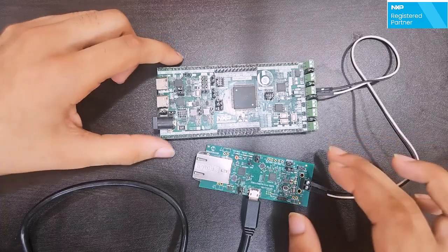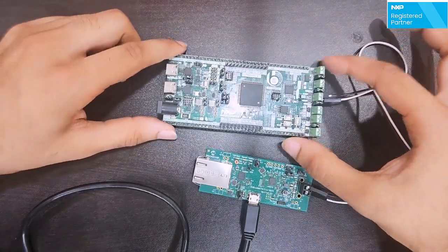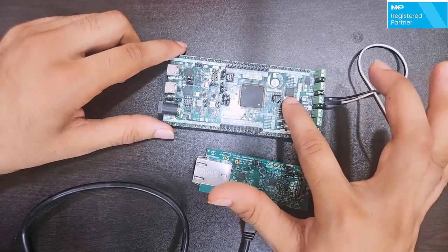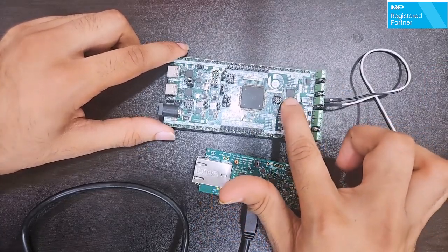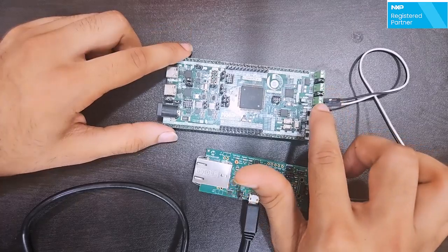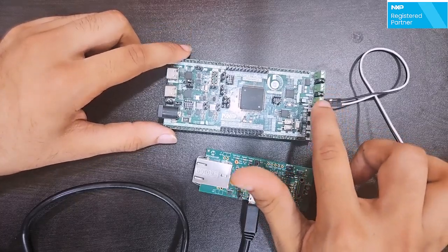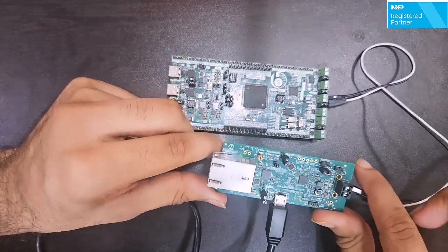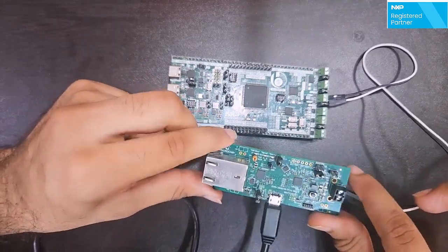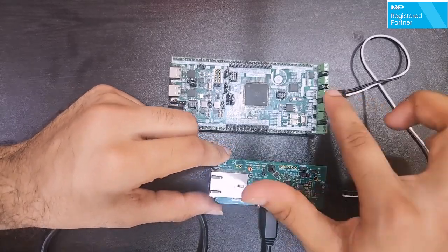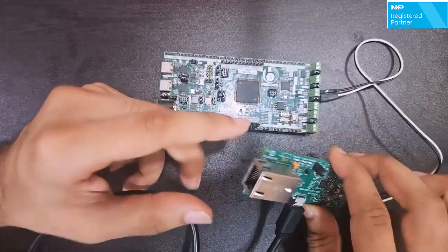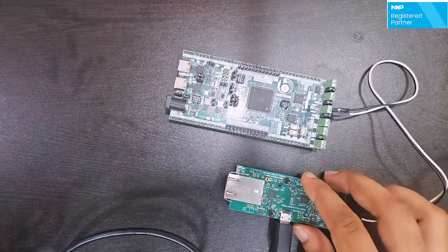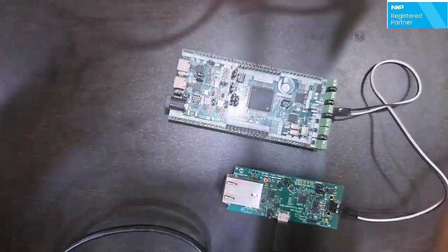Now, in terms of the connection, this is our Autoboard version 1, and as I told, this is our main controller K344, followed by an Ethernet transceiver IC TJA1103 of NXP Semiconductors, followed by a 2-pin terminal connector for connecting the automotive Ethernet. And this is the Ethernet media converter of Microchip Technologies, which is used for converting the automotive Ethernet to the standard RJ45 Ethernet connection, which will be connected with the RJ45 wire.